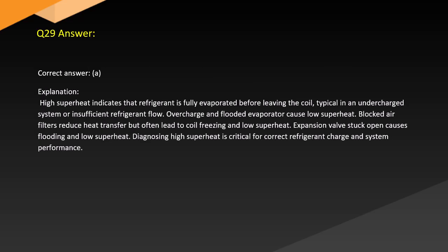Answer. Correct answer, A. Explanation. High superheat indicates that refrigerant is fully evaporated before leaving the coil, typical in an undercharged system or insufficient refrigerant flow. Overcharged and flooded evaporator cause low superheat. Blocked air filters reduce heat transfer but often lead to coil freezing and low superheat. Expansion valve stuck open causes flooding and low superheat. Diagnosing high superheat is critical for correct refrigerant charge and system performance.